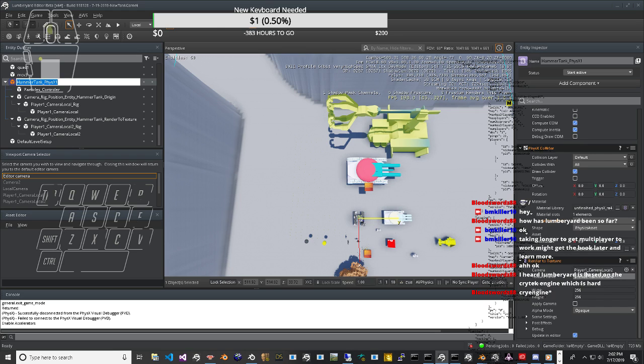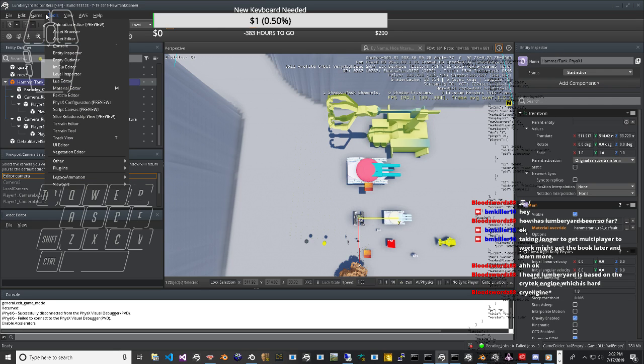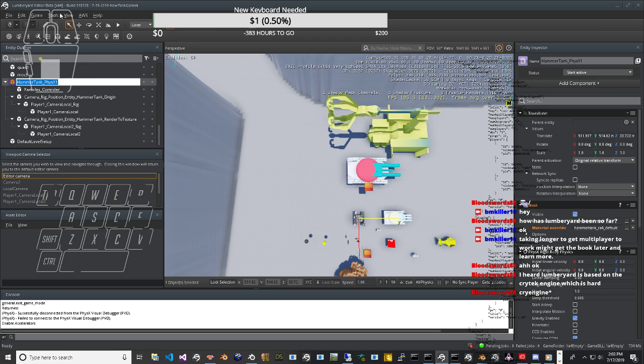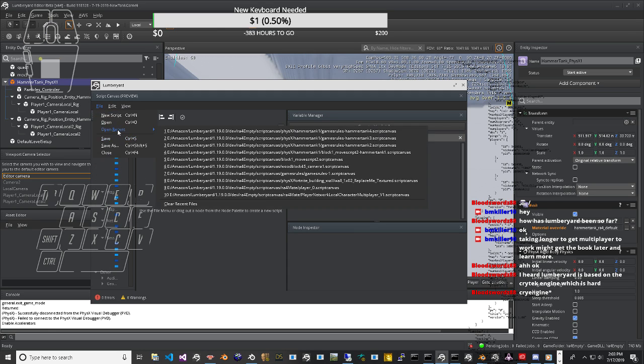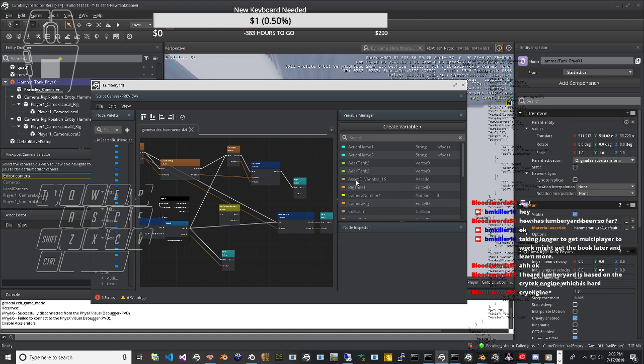Drivers in high-speed circumstances can also generate desired aerodynamic forces, as in slipstreaming, in the slingshot pass, and in the Earnhardt tip maneuver, where the driver takes the air off the spoiler of the car in front of him. Tires generate forces by sticking and sliding and everything in between. They transmit these forces to the wheels by elastic deformation. The elastic deformation is extremely complex and theoretical computation requires numerical solution of finite element equations.